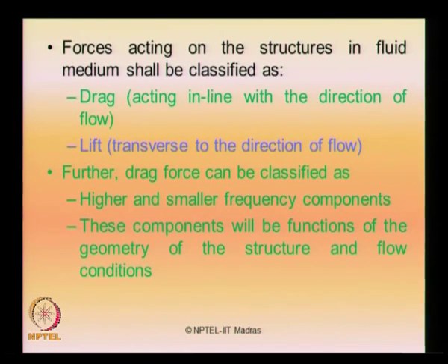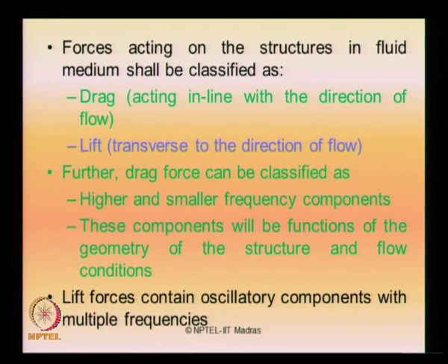If you look at the drag force in general, this can be further classified into higher and lower frequency components. Drag has two distinct frequency components: one is higher frequency components, the other is lower frequency components. These components will of course be functions of the geometry of the structure, and they are also influenced by the flow conditions. If you look at the lift force, on the other hand, lift force contains essentially oscillatory components with multiple frequencies. In drag force you can distinctly identify two frequency contents, higher and lower, whereas in lift it is a mixture.